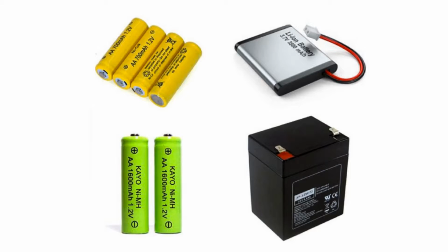Lithium-ion and lithium-ion polymer batteries have a voltage of 3.7 volts with a power density of 126 watt-hour per kilogram to 185 watt-hour per kilogram. Lithium-ion batteries are ideal for mobile phones and similar mobile devices. Lithium-ion polymer batteries can be found in drones since they provide more power, are robust and flexible, and have a lower chance of leaking electrolytes.